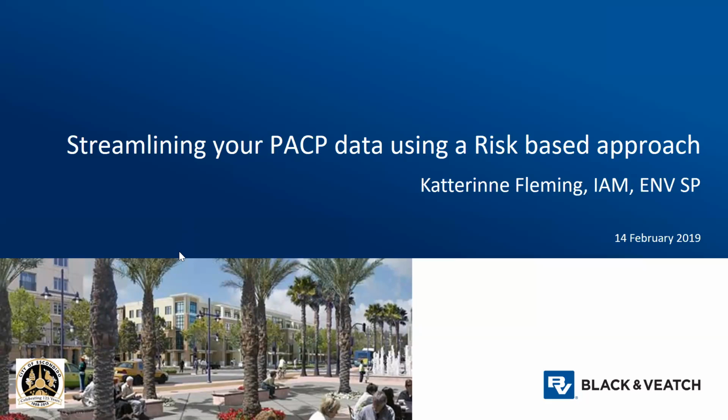So first and foremost, I wanted to thank those attending this webinar and for the opportunity to present today. This presentation will describe the development and outcomes of the City of Escondido's ongoing evolution of their CCTV inspection tool, GraniteNet, integrated to their CMMS system, which they use as CityWorks. And then how we were able to help the city streamline that PACP data from the CCTV inspections and use a risk-based approach to grow awareness of the shape and condition of those pipes that were selected for this pilot.